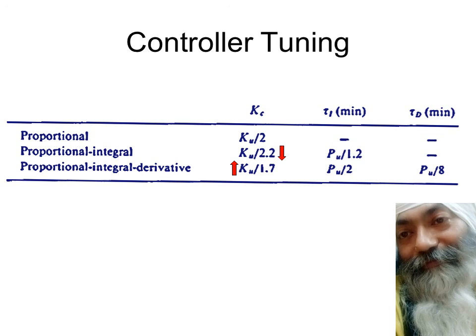So my dear friends, you can actually do this practically in the labs, on the simulators and Simulink and so on. As the time comes, we shall be doing it in the practical labs also. But the Ziegler-Nichols method and Cohen-Coon, whichever may be applied, is a very good starting point to know the tuning of the PID controller, which can further be refined by many methods. I've been telling you again and again to get the values of the gains of proportional, integral, and derivative control. So this is all about controllers and tunings.